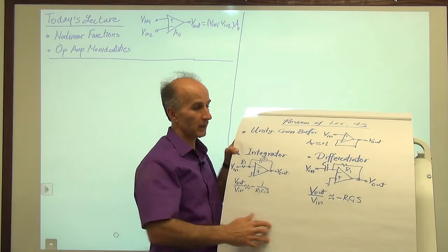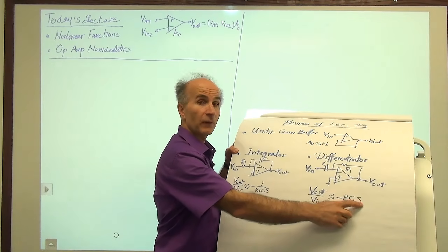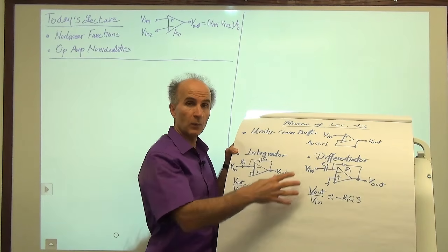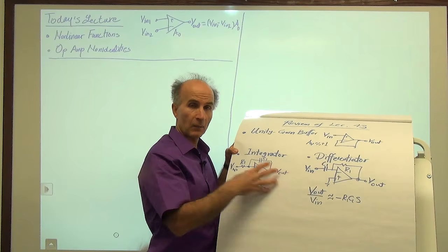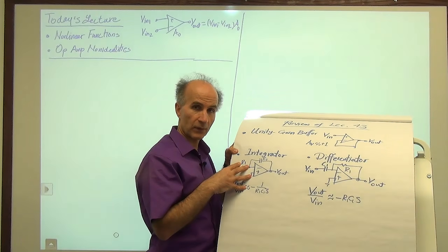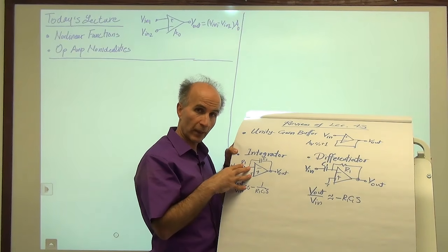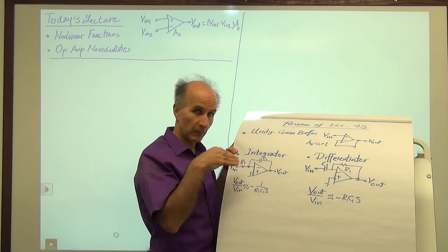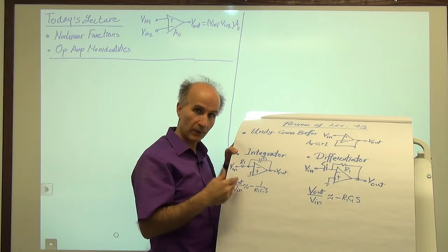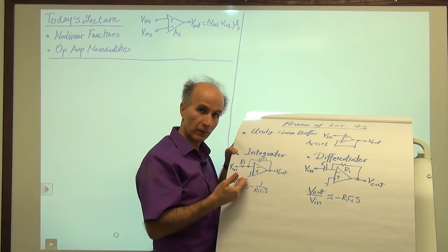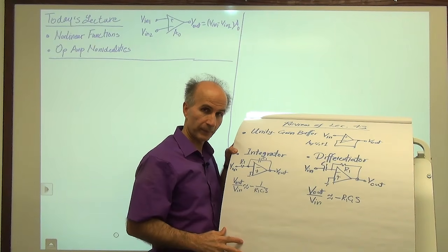We saw that because this circuit tends to amplify high frequency noise, we don't use it very often. Most often we use integrators. In other words, even if we have a differentiation somewhere, we try to maybe integrate both sides or something so that we do end up with integrators, not differentiators.